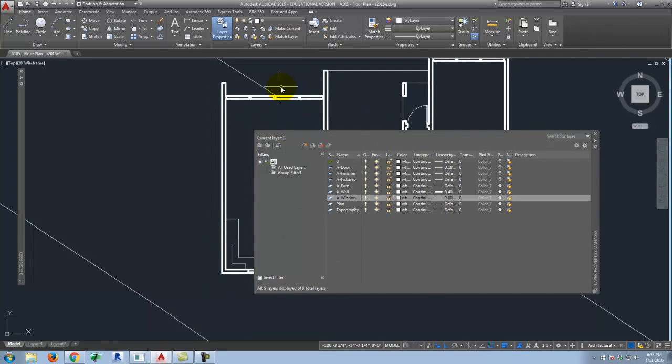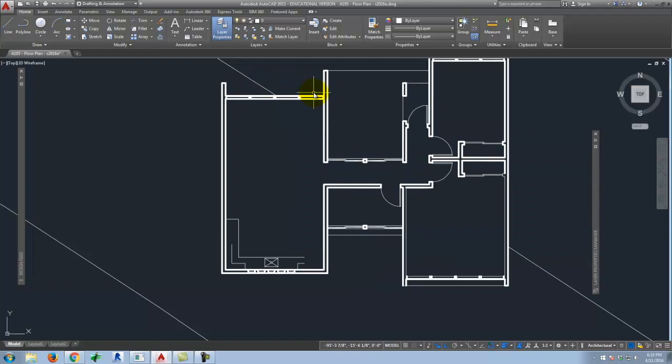By the way, if you were going to laser cut something, the line weight needs to be 0.00. So we'll get to talking about laser cutting a little bit more down the road, and certainly those of you in 121 will end up laser cutting this semester. The important thing to remember is 0.00 is what you're after for that line weight. OK, so I've now established the basics of line weights.